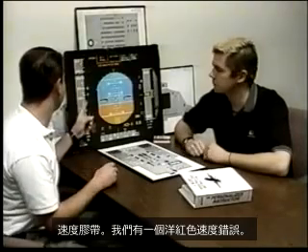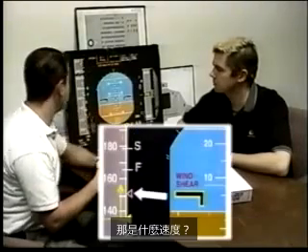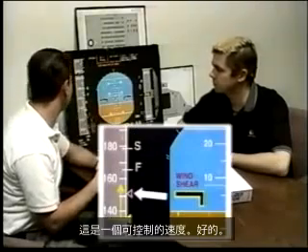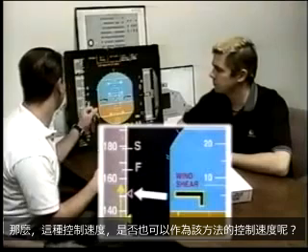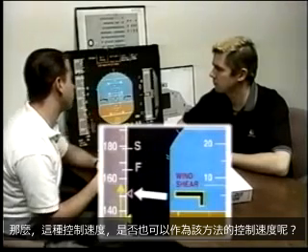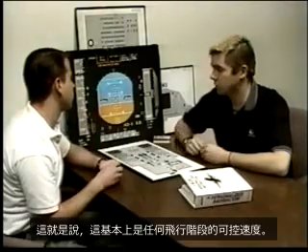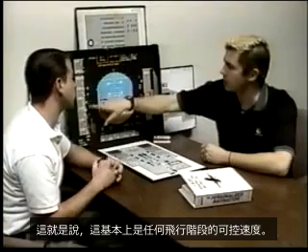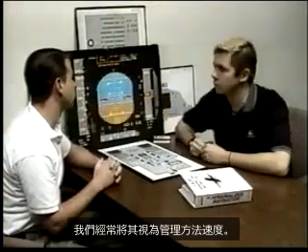On the speed tape, we have a magenta speed bug. What type of speed is that? That's a managed speed. Okay. And that managed speed, could that also be a managed speed for the approach? Yeah, it's a managed speed for basically any phase of flight. We regularly see it as managed approach speed.